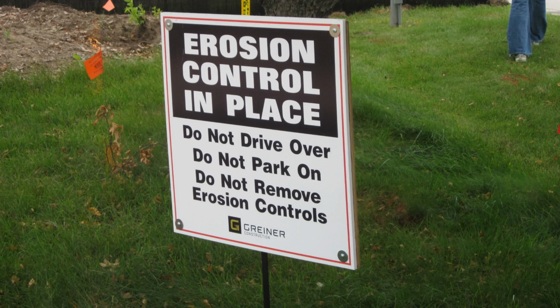Vegetative cover along roadsides helps prevent soil erosion, which can significantly impact the environment. Stormwater runoff washes sediment, fertilizers, and pesticides into waterways. Nitrogen and phosphorus carried by runoff causes many environmental problems, including excessive algae growth, depletion of water's oxygen supply, and suffocation of aquatic organisms. Topsoil washed away by storm runoff clogs waterways and reservoirs with sediment, and excess runoff contributes to flooding problems in downstream areas.